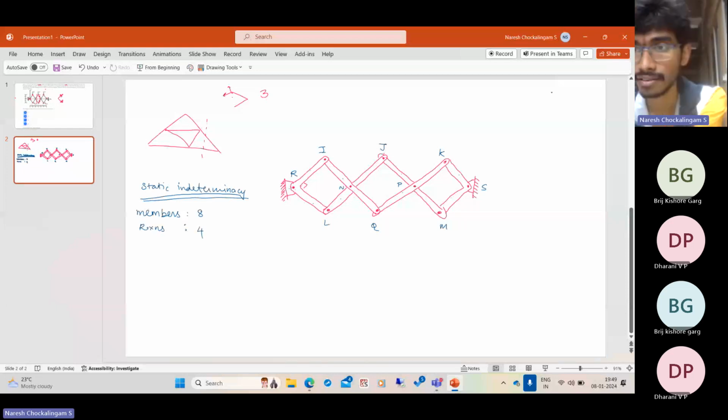It is the pin. So there are like this. It is pinned here. And for simplicity, let us say we are supporting the scissor with something. Right? So if you look at this, it is actually a statically determinate structure. The reason is that if you take the unknowns, let us take this as one member, this as one member. So you have two members, but the two members are free to deform themselves, right? They have some force which is holding them together, which is the pin force. Pin force has two components. It doesn't transmit any moment, but it has got two components.